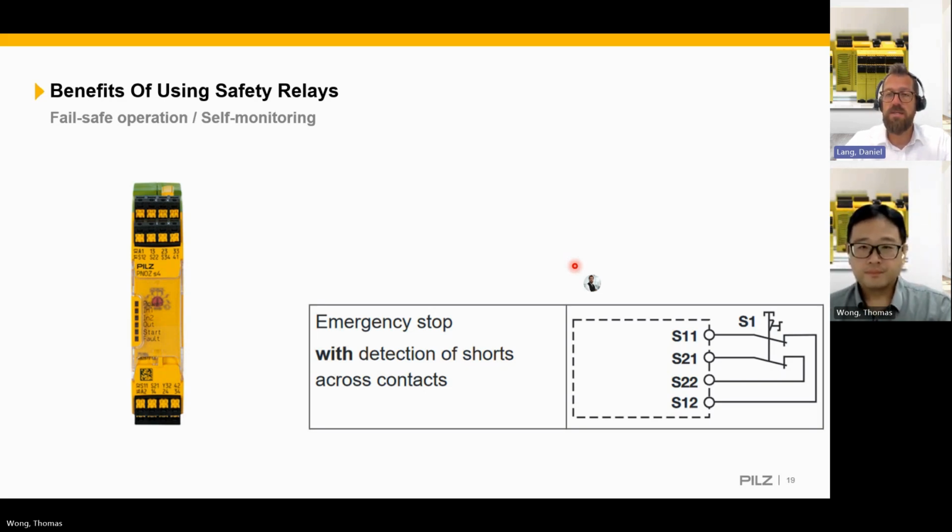And this is also a very good thing: if you wire from these input channels, for example the e-stop, the S4 or most of the safety relays will emit so-called pulses for the connection of the safety input.